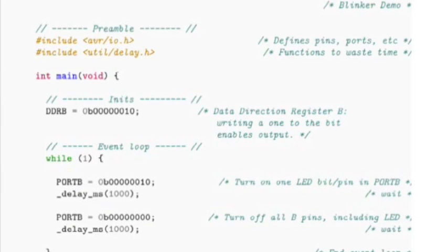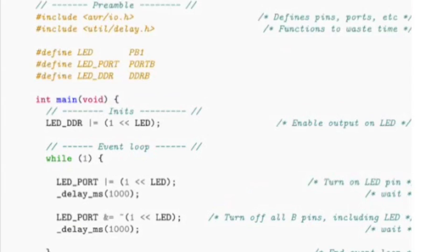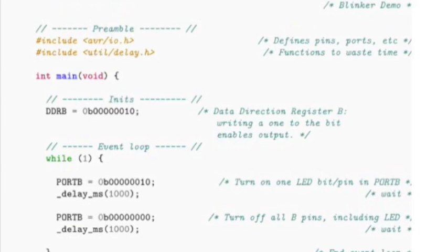The way I would write this, or at least a little closer to the way I would write this, is the following. Imagine that you wanted to change this code to work with a different pin. Maybe you put your LED on PB0 or PB3 for all I care. You have to change all of these numerical values everywhere that this occurs in your code, and that's lousy.